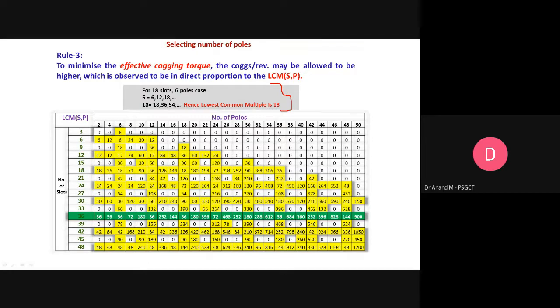This is a key step, where the designer's choice for e-vehicle application comes in at this stage. Maybe we can have a very good selection of a lamination material, maybe a magnetic material, maybe a magnetic orientation, maybe a core orientation, but the number of rotor poles and the number of stator core slots per pole is going to be of paramount importance for designers in e-vehicle applications.